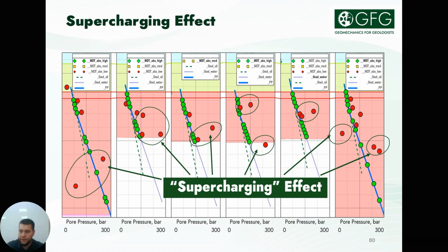When drilling, the pressure difference between the wellbore and the surrounding formation leads to the invasion of mud filtrate into the formation, while solid particles accumulate on the wellbore wall, creating a filter cake. Within the wellbore, the pressure is maintained at a hydrostatic level, but it rapidly decreases across the filter cake, and then gradually drops to the original pore pressure at a certain distance from the wellbore.